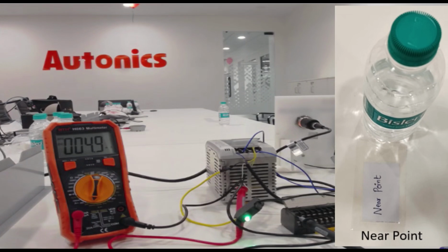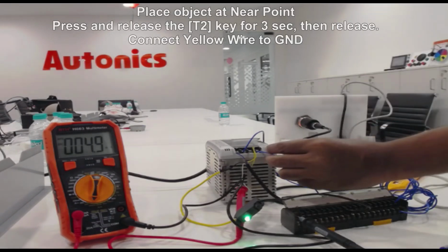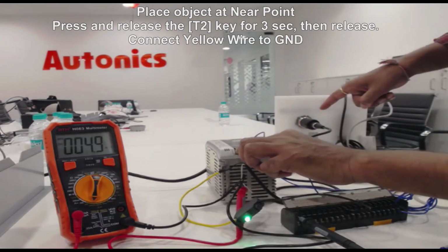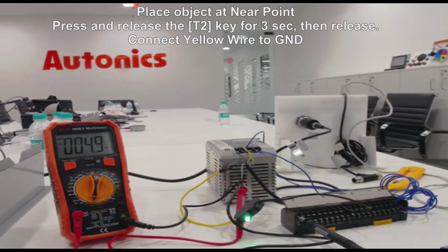Before starting to teach, make sure your object is placed at the near point. And then you need to press the T2 key. For T2 key, the yellow color wire should be connected to ground. For 3 seconds, 1, 2, 3. Near point has been taught.